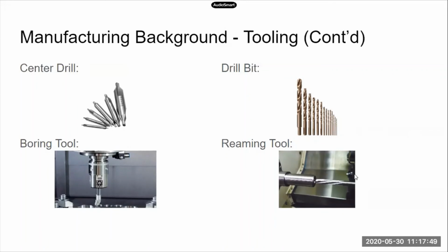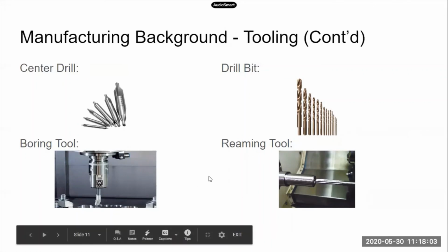Boring tools and reaming tools both basically do what the drill does, except it's not that initial cut. It's more like a finishing pass to hone in on the exact diameter that you want. Makes the inside really nice. It's not always necessary though.